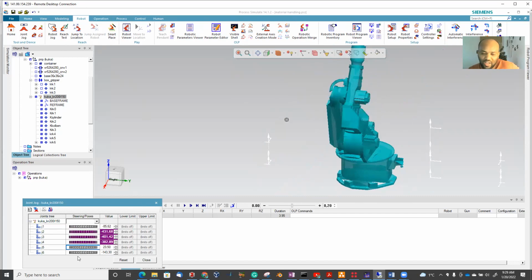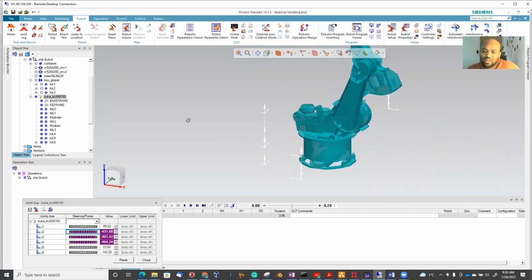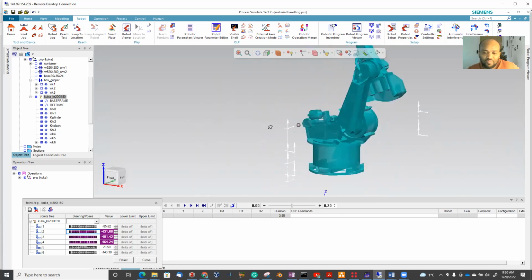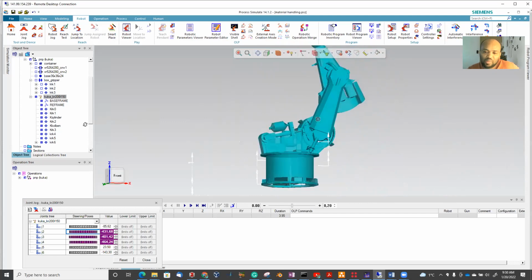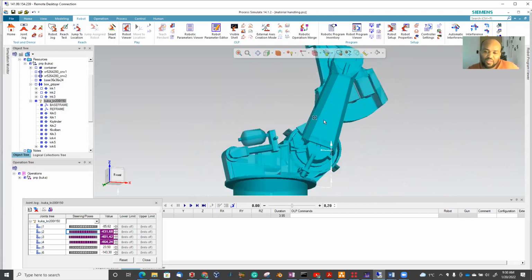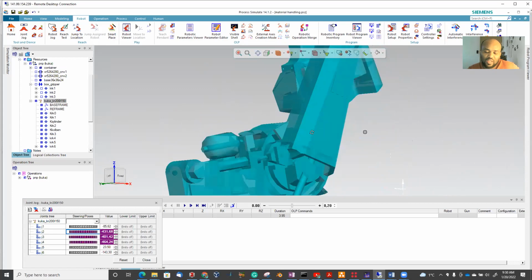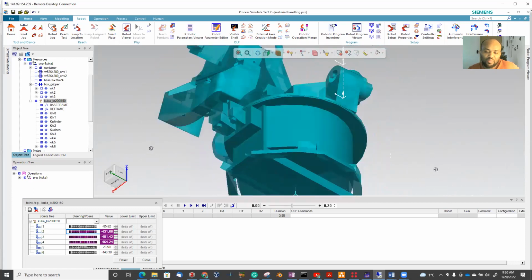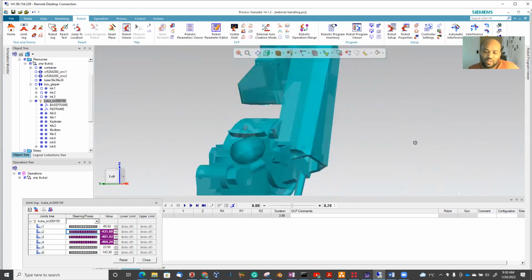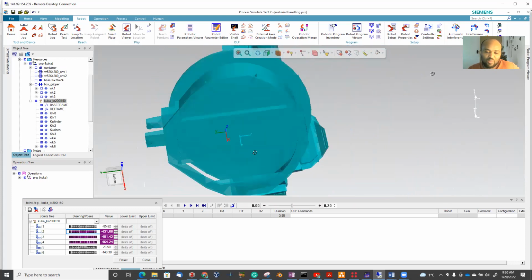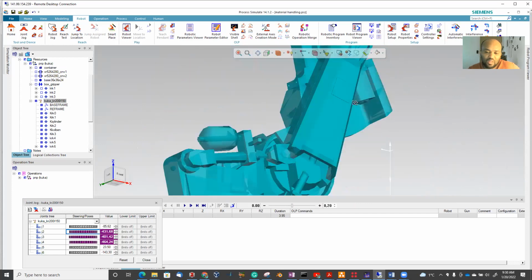So I would like to have a dynamics property where the robot is controlled for its dynamics as well. For that, I would like to know the mass property, the center of mass, the center of the reference frame, and also how the derivative of the transformation matrix behaves.